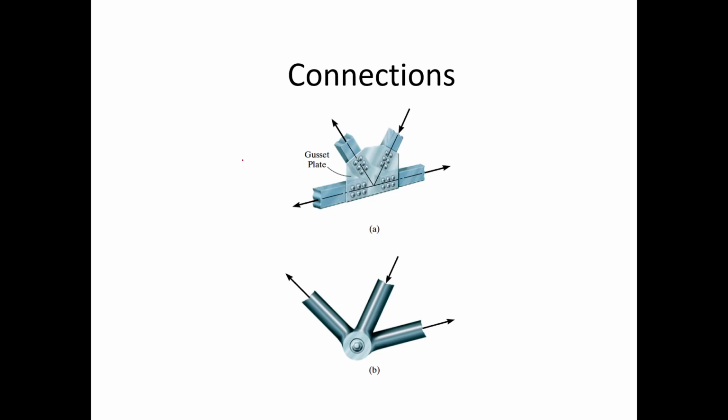For actual practice, it will be bolted, and then placed with a gusset plate, and then a weld for further fastening of the bolts. Or it could be that there are no bolts, but it's purely welded. Again, it will depend on the structural details.